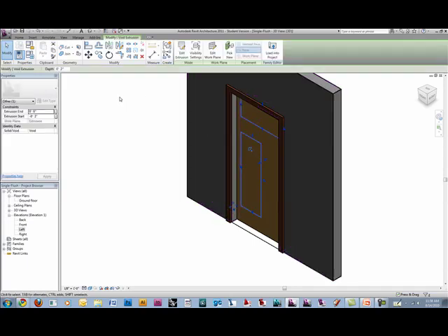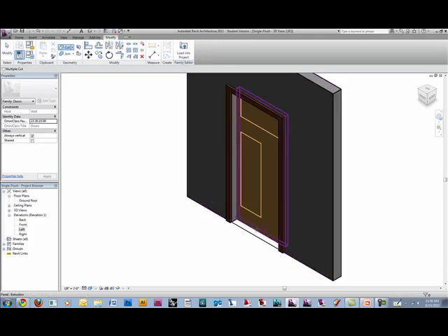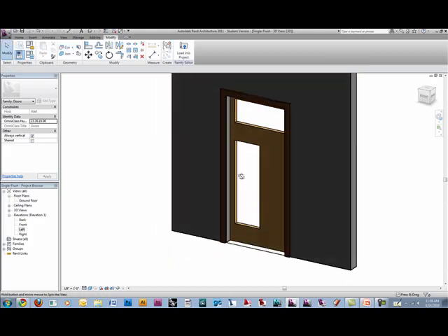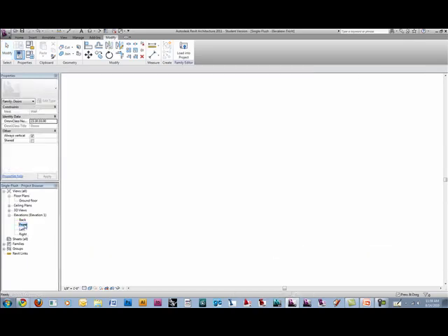They're big, but say if I want to do a tinier one where I'm just cutting out maybe a door hole or something, you'll never find the void. It's really difficult, especially if you do it a long time. You'll just end up losing them. So I'm gonna go to cut, and I want to cut those holes out. So click the solid geometry first, and then the voided geometry. So now I have 2 holes through the door, but I want these to be glass, right? So let's make them glass. And to do that, we're just gonna go back to the front.